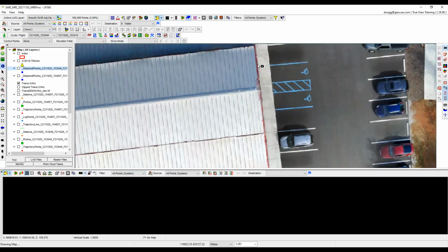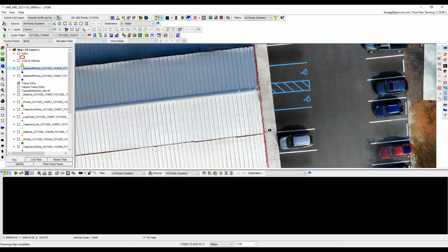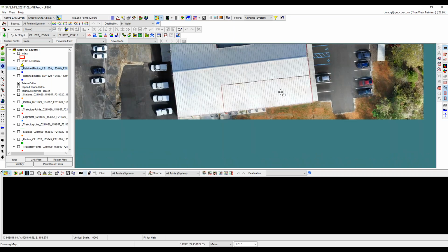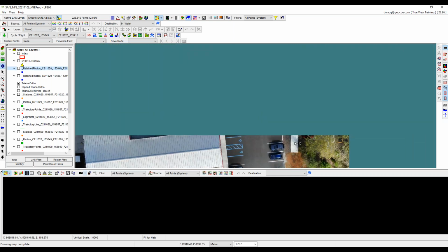There can be some issues around the edges because I'm using a point data set, and that's where I said if we put some vector elements in here, we can clean this up and make this a little cleaner along the edges of features. Same thing happens when you get things like retaining walls. Sometimes you get some digital elevation model that kind of spans across that, and so it gives you a chance to hold that surface a little nicer.